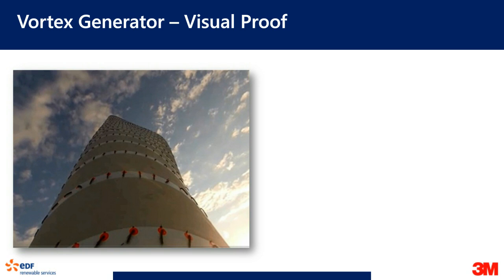Now, as we move forward, you can see the flow tufts are basically in parallel to the blade direction and perpendicular to the wind direction. So that's a problem. That means there's something happening where the flow is not attached to the blade. In turn, there's a flow separation, in turn causing stall, and finally output loss in AEP. So this is what we are trying to correct.